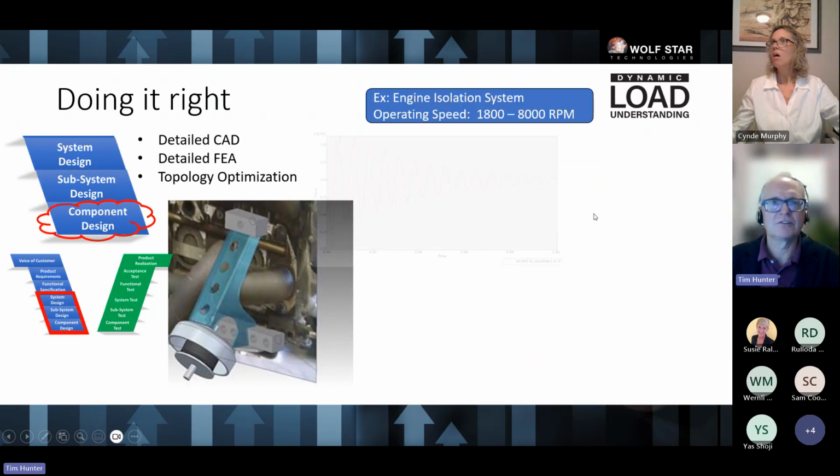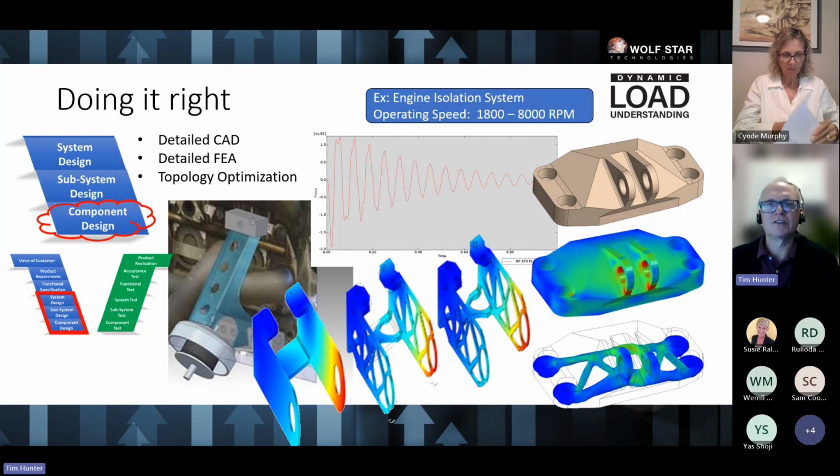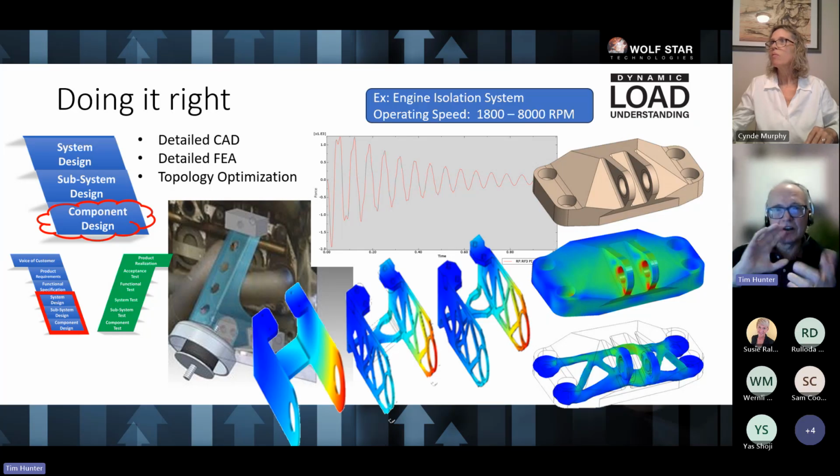And so the whole idea here is that we're going to basically go in and take the CAD models, take the shaking forces that we're putting into them, and now we can leverage things like topology optimization. So topology optimization is critical here because now you're going to get down to the minimal mass that your structure needs in order to withstand the loading that you're putting onto the system, okay? So this is just part of the critical ways of going through and optimizing and getting very robust structures.